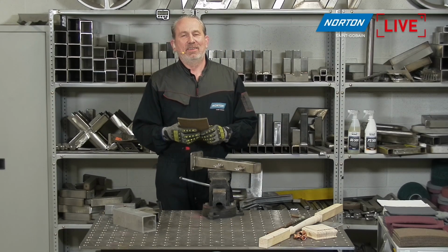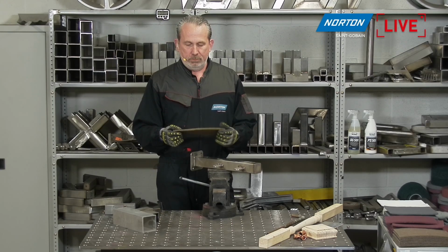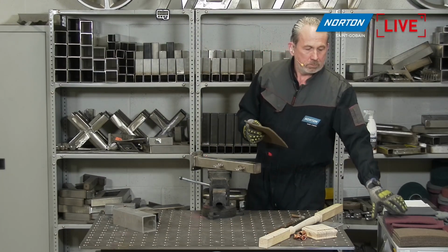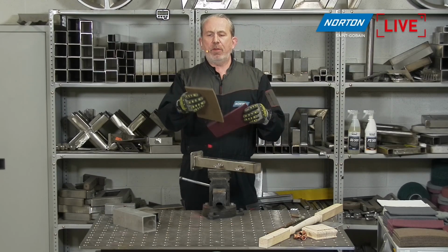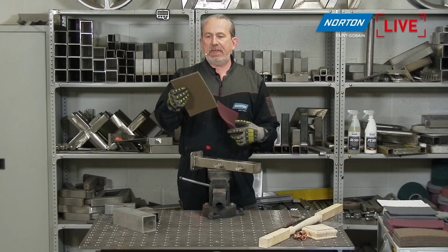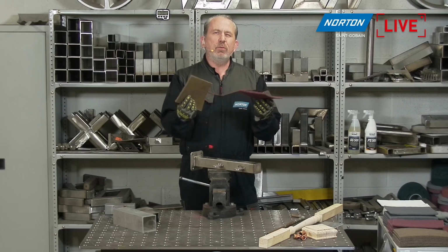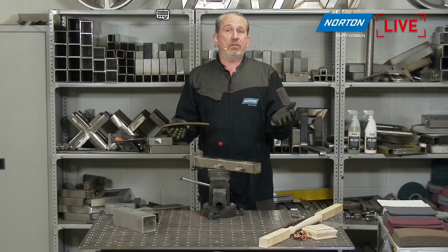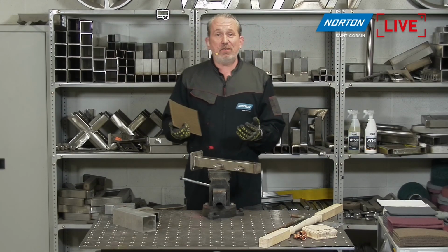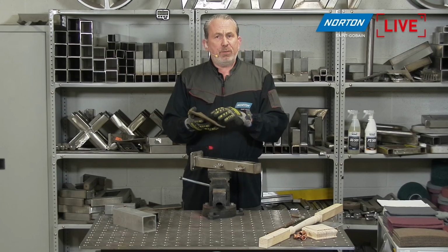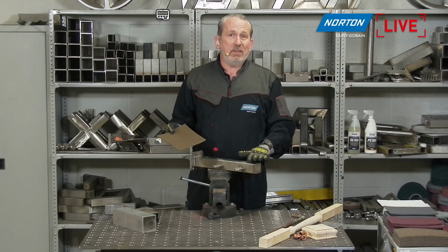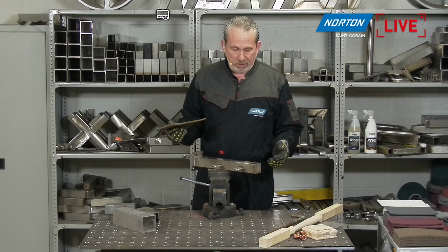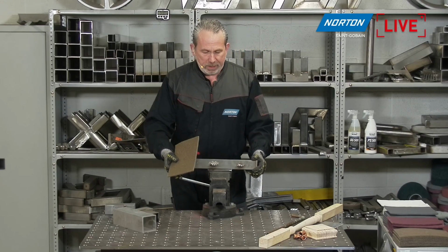So with this brown heavy-duty pad, we have more aggression. It carries an even stronger structure than the maroon pad that Paul's. You can feel that when you have the pads as well. The fibers are a different size. The denier, the fiber inside here, and the amount of resin here is a much stiffer, more robust feeling pad than the other ones. And that's because, as you say, Robin, it's for more aggressive applications. So it needs to be able to withstand. And also, if we have a soft structure, it's not going to push the abrasive grain into the material very well. So we need it to be harder with a coarser grain. It's quite as simple as that, really. Otherwise, it doesn't work.